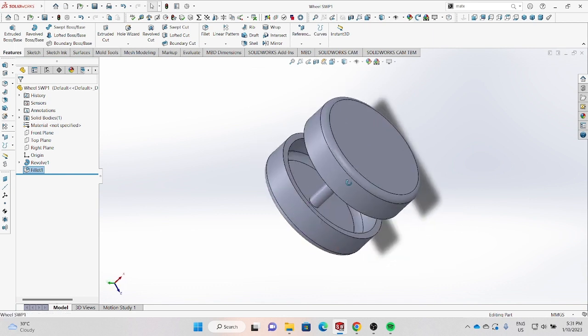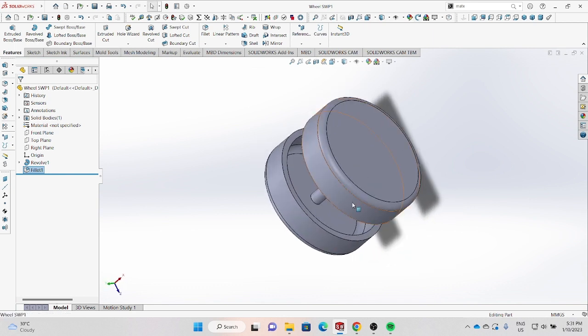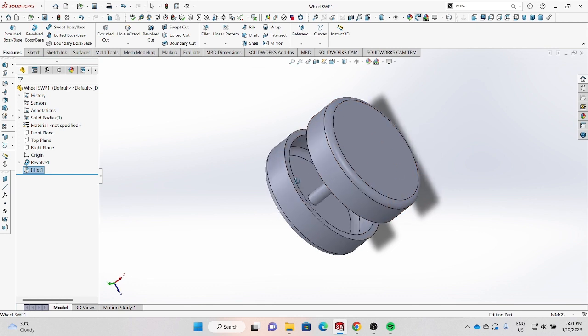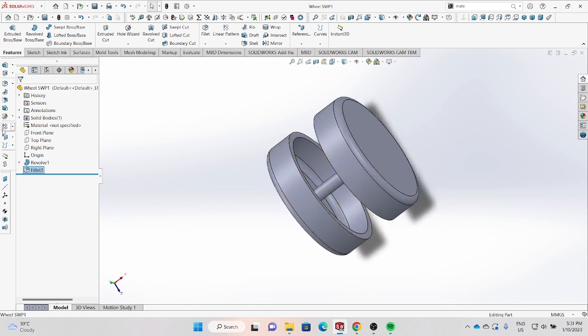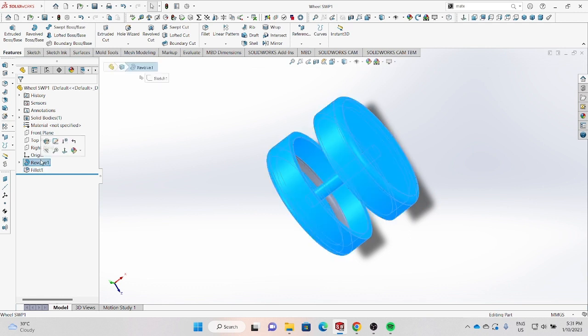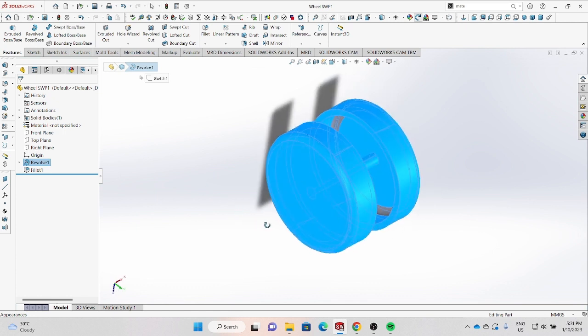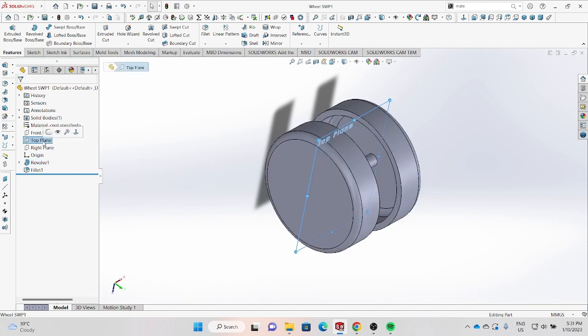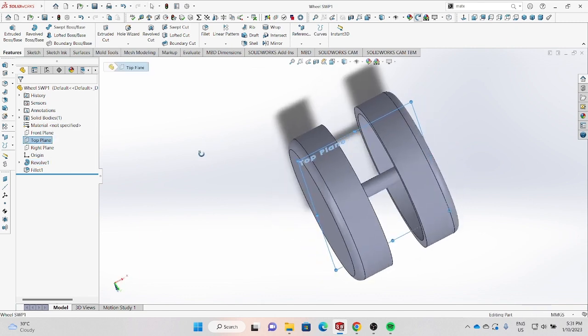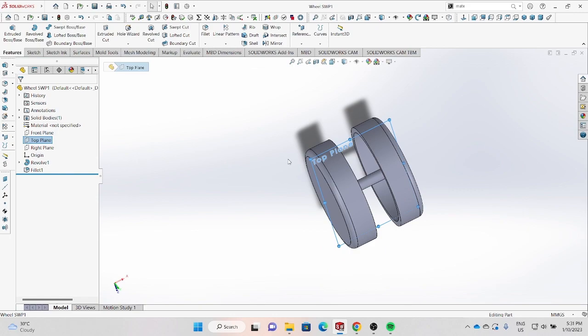For the wheel part, first sketch on the right plane, set 45mm for the width to the left from the origin, and the height is 30mm. Continue to sketch a line from the height and set 50mm to the right. After the sketch, click revolve, and for the axis of revolution, select line 1, and under direction 1 for the reverse direction, select line and set the angle to 316 degrees.